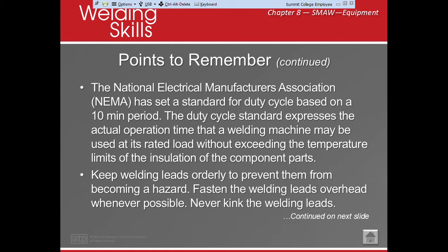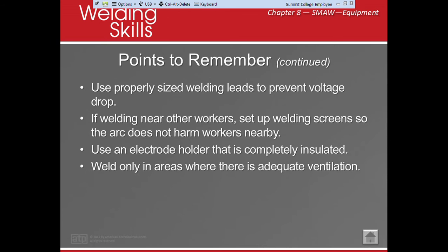We want to make sure that we keep leads orderly to prevent them from being a tripping hazard. We also want to make sure that we don't kink them, and if there are any burns, cuts, anything like that, that we fix or replace them. We also want to make sure that we use properly sized leads to prevent voltage drop.